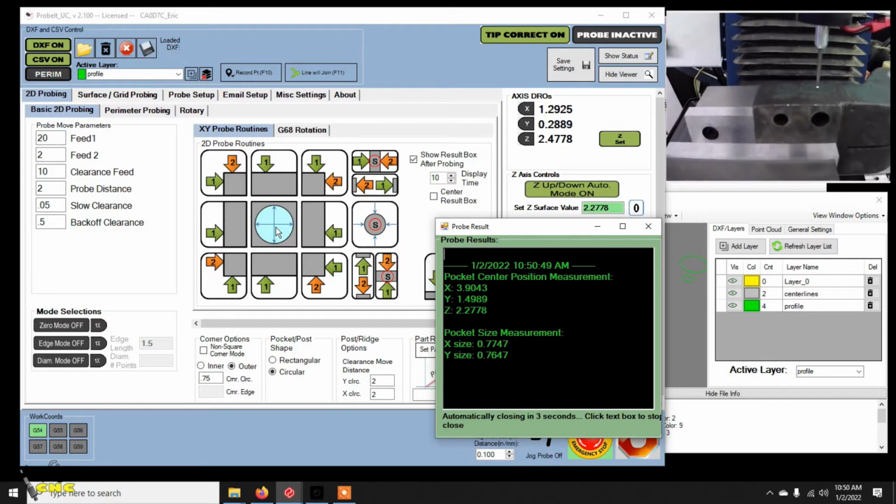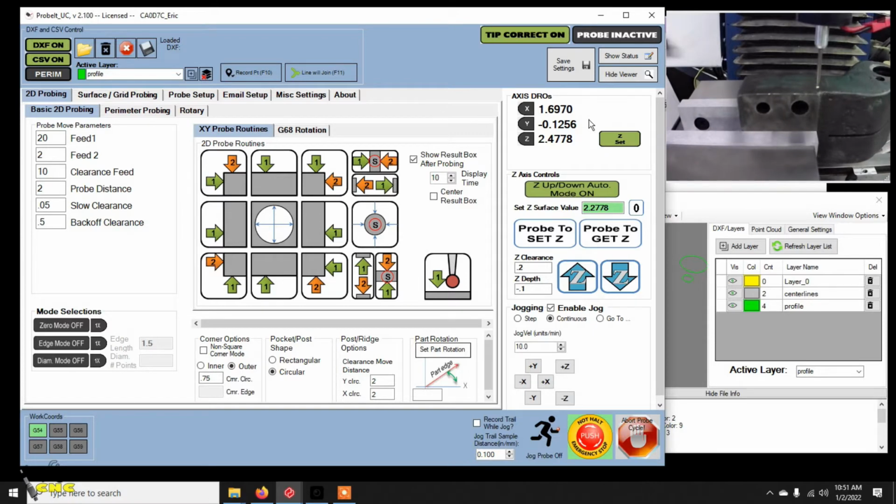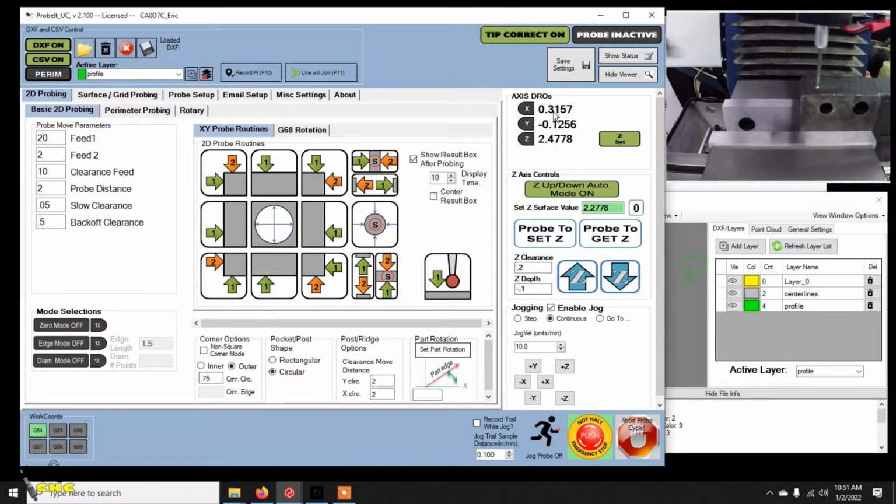So to establish a good edge here, we've got a nice machined reference surface. Let's eyeball the length. If you remember, this corner over here is 0,0 for X and Y. So if I travel over to this side, it tells me X is about 1.7 inches long. I'm going to come over here and roughly position it. We've still got auto up down on. I'm going to put it on edge mode in the Y direction, and we'll say our edge length is 1.5.